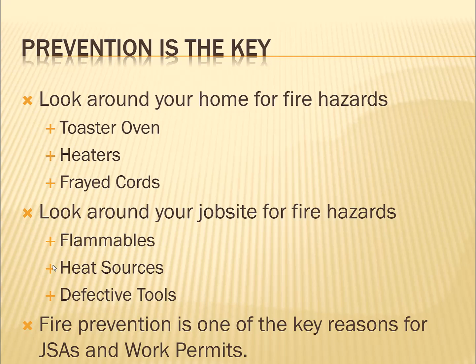For instance, if you're going to do some welding, you shouldn't really be doing that around flammable materials. Sometimes, though, you cannot do that. Maybe you can't move the flammables. Sometimes you have to protect the flammables with fireproof blankets and other techniques like that.